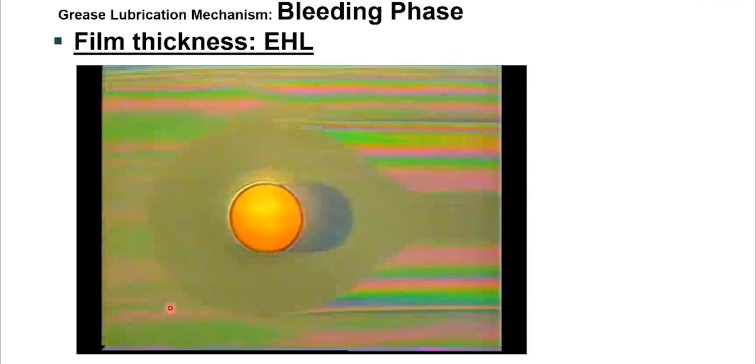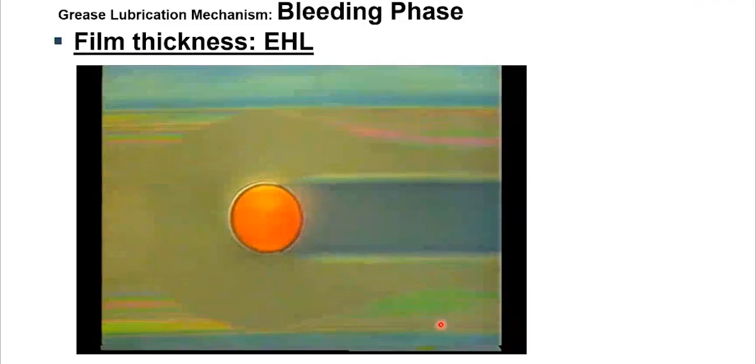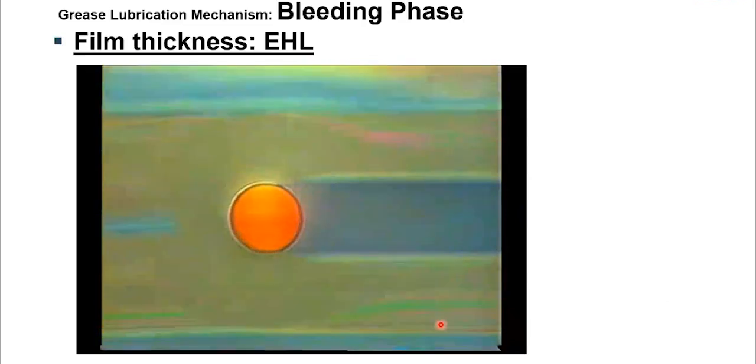So in the beginning, when you have a lower speed, you still witness the fully flooded situation, because oil replenishment happens to the contact quite easily. Rolling is not so fast. When you increase the speed, now we slowly started to increase the speed, the replenishment is very difficult to happen. The lubricant supply into the contacts will be minimum.